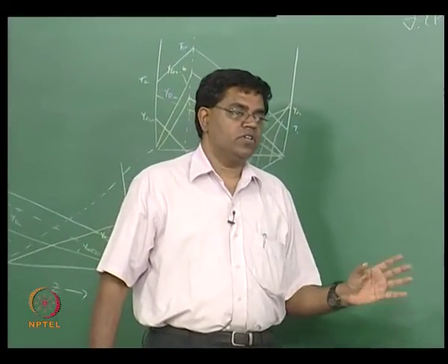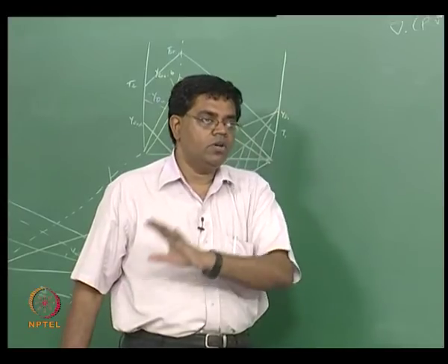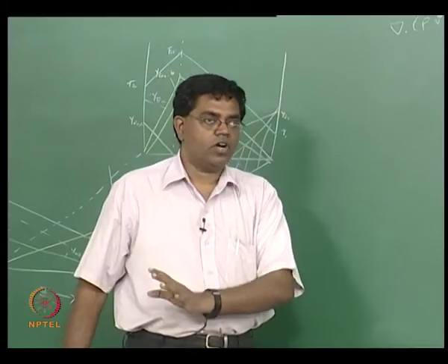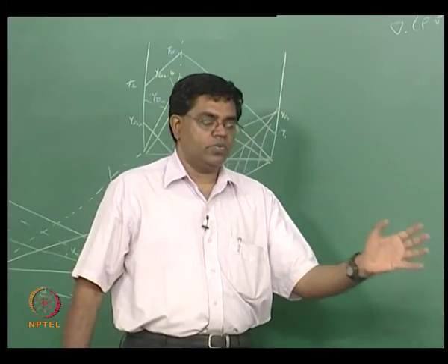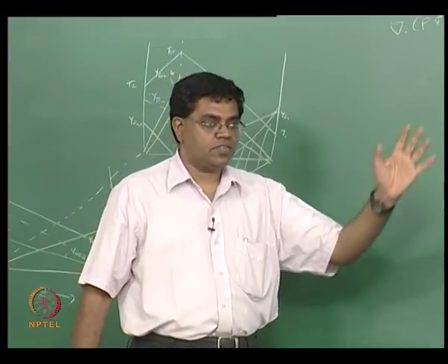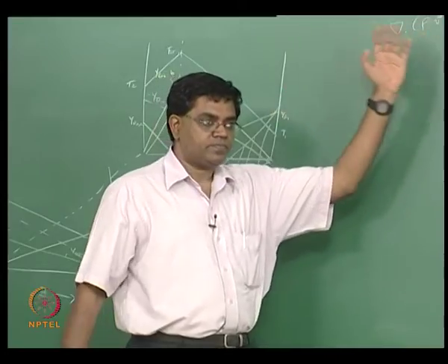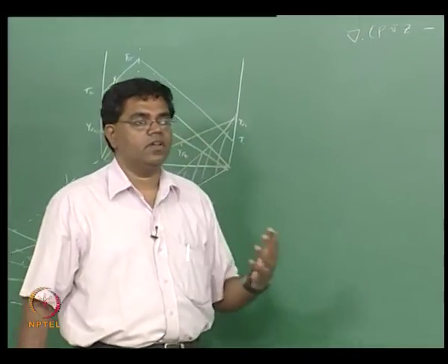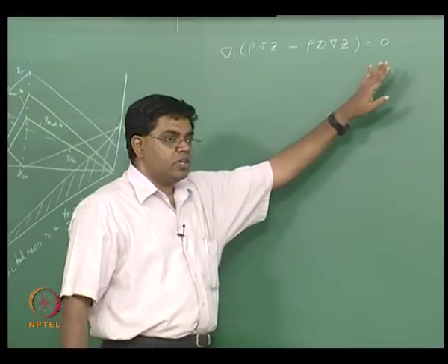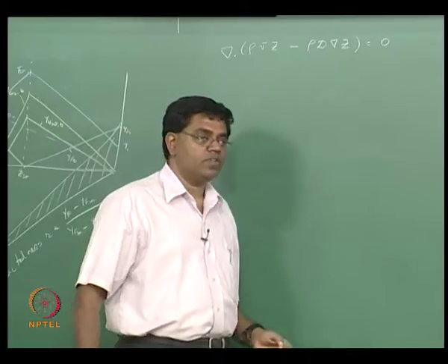So no matter whether carbon is present in the hydrocarbon or carbon dioxide, no matter whether hydrogen is present in a hydrocarbon or water, no matter whether oxygen is present as itself or as part of carbon dioxide or water, the mixture fraction gets conserved because it is based on element mass fractions, and therefore the reaction rate term will not show up when you try to write an evolution equation for this.